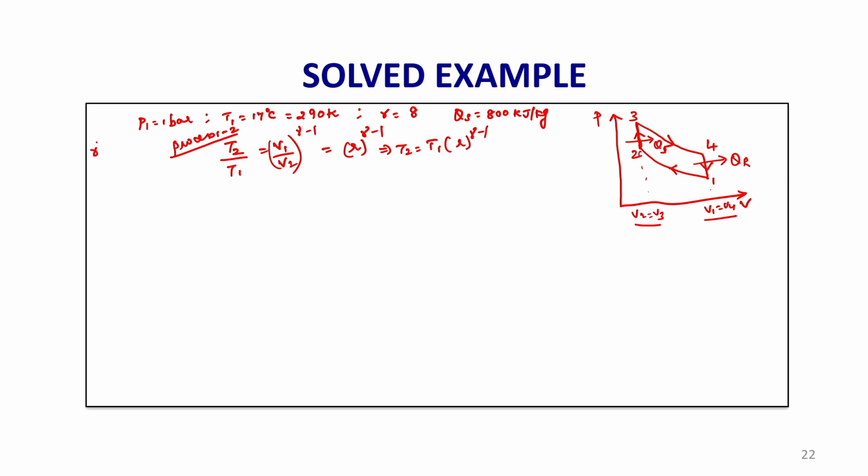Gamma is equal to 1.4 for air, and the working fluid we are considering in the air standard cycle throughout the cycle is air. Now, T1 is given, it should be substituted in Kelvin, r is the given compression ratio, and gamma is 1.4. So, we can find out the temperature T2 at the end of compression.